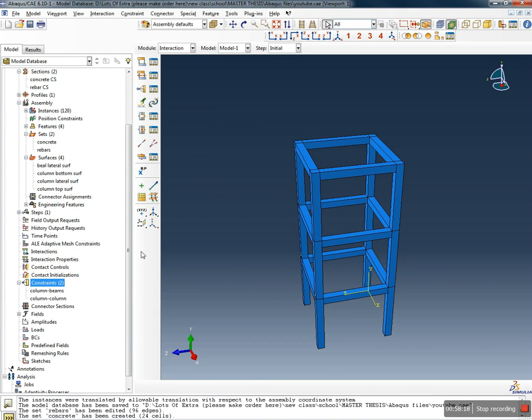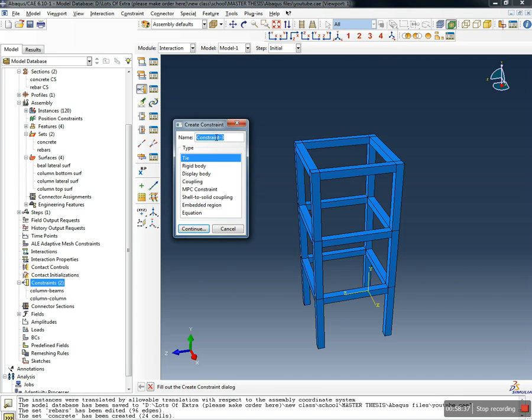And here normally if you don't get any errors that the surfaces don't match or don't fit or something like that, it means that you have a correct geometry from this point of view of tying. And now the last tie that we have to do right here is that we have to embed the embedded rebars. We're gonna keep the name as we wanted to give in the beginning, and this will be embedded region,